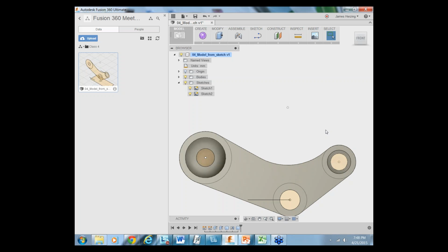So is there a best practice on when you do that cut? As long as we drag beyond it, it's okay, but if we go back later and... Okay, so the question was, is there a best practice for the cut command, just dragging through stuff? Sure, the more accurate you are, the better. I'm just thinking about if later on I go back and make my rocker arm wider, a subsequent cut might not go through. Right, so that's true. If you make your rocker arm wider, it might not cut through. If you have additional geometry that you then add, it might cut through that.